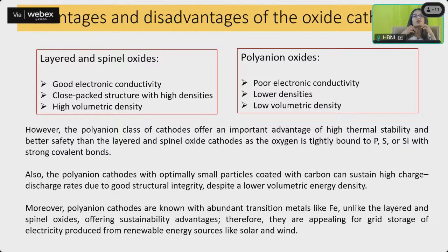See, in your battery material, you must understand what is happening. You have your electrolyte and your separator. Both of them are basically ion conducting, but they cannot conduct electrons. So electrons have to go through the external circuit. Inside your battery, the ion movement is happening inside, and the electron movement is always happening outside. Your electrolyte material is ion conducting, but it shouldn't be conducting electrons. Similarly, your separator material should be permeable to the ions, but it shouldn't allow any electron to pass. So electrons have to move through the external circuit.